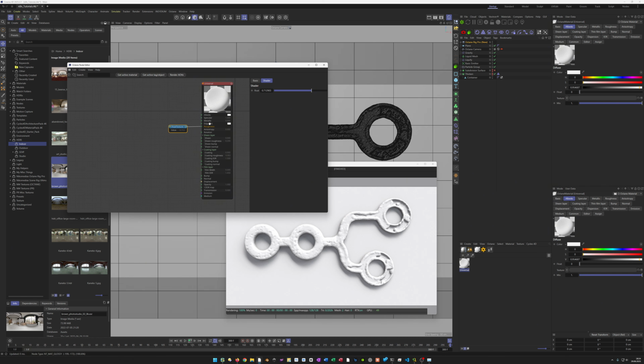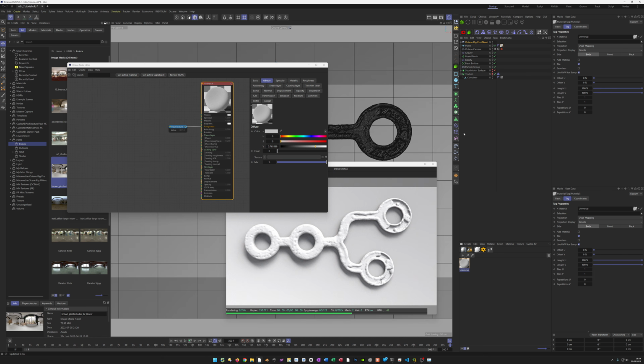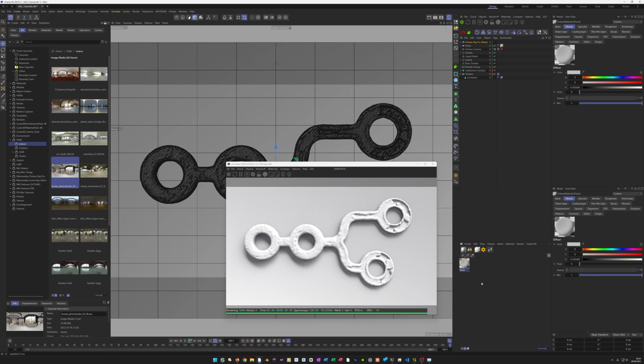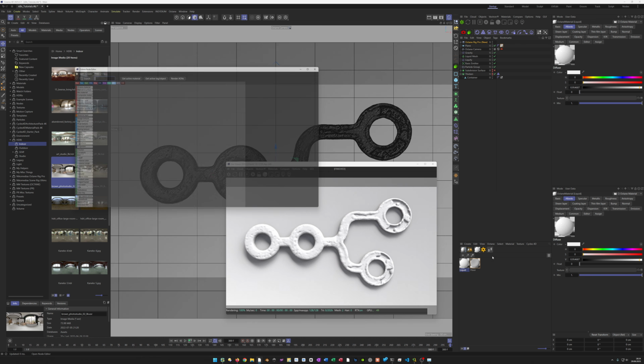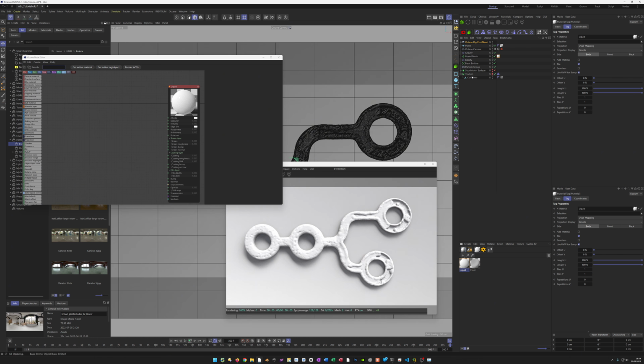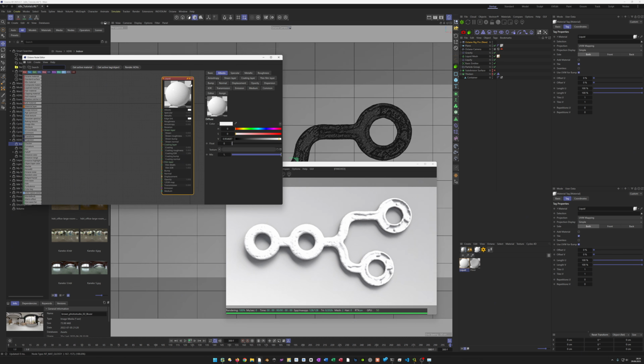So, and in the albedo, I make it a little gray here, and put it on my plane. The next material, I name this floor. And the next material will be the liquid. Here I make a transmission, so plump the liquid on the liquid mesh. And here we need transmission. We go to specular, float all the way up, and the albedo here has to be black then.